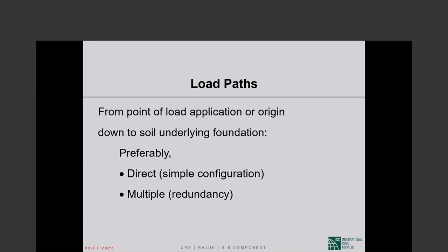BNBC seismic provisions are, compared to ASCE 7, I don't want to say incomplete, but major topics are simply not covered. Redundancy is one of them. Redundancy is mentioned, but the ASCE treatment of redundancy is not to be found in BNBC 2020.